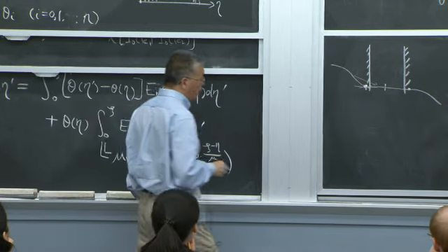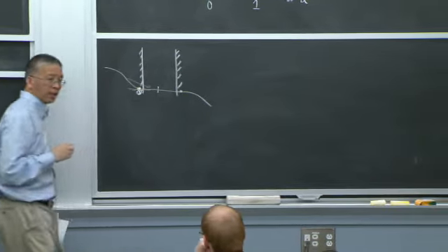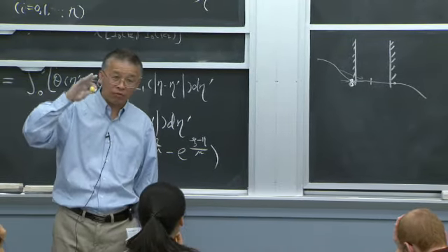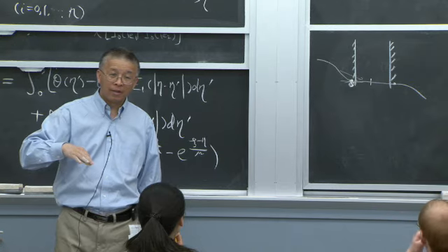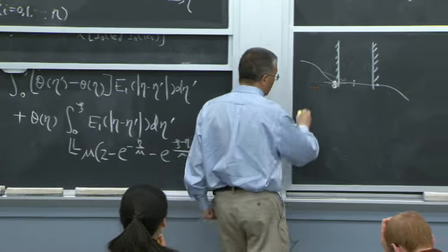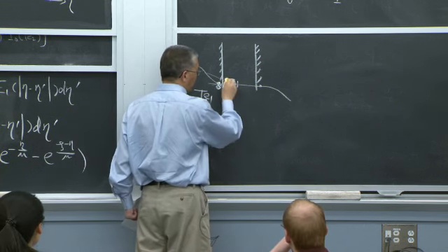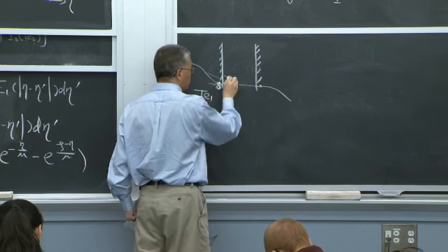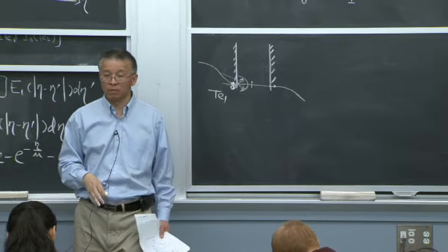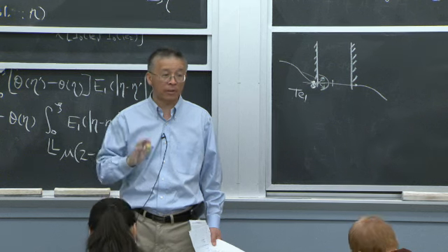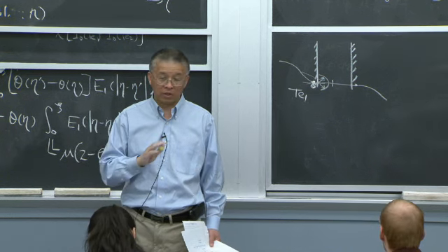And when you put a thermocouple into this solid, what you measure is the solid temperature, that is, the lattice vibration. Okay, so this is my TE1. What I say is this is the photon temperature, and equivalently, when they emit, I say it is half of the space they emit as a black body. So that's where my physical temperature jump comes from in the case of photons.